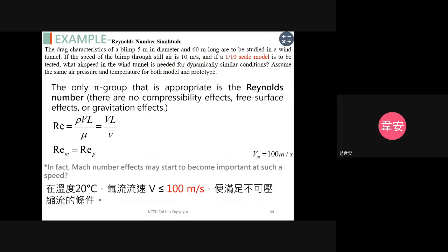If the speed of the blimp through still air is 10 meters per second, and if a 1 over 10 scale model is to be tested, what airspeed in the wind tunnel is needed for dynamically similar conditions? So we assume the same air pressure and temperature for both model and prototype.